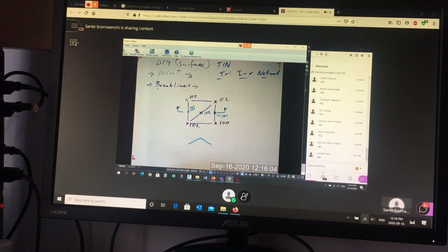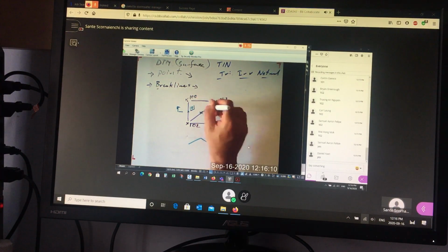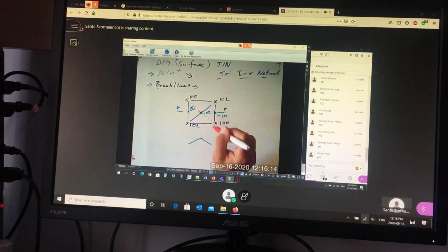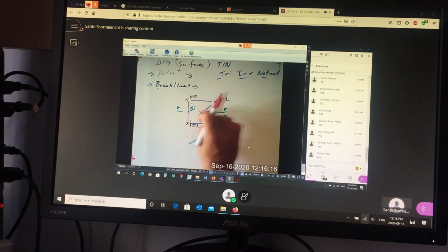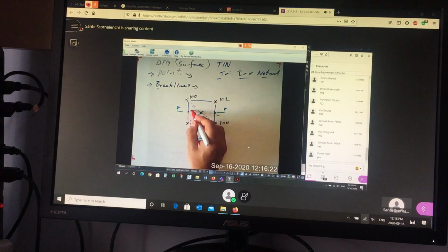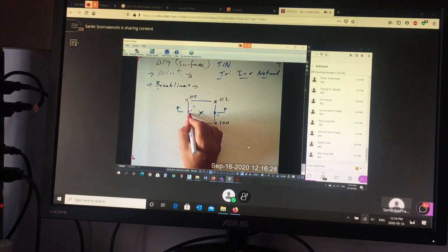Okay, so now I'm going to look at a different solution for the triangulation. Instead of this diagonal, what if the solution was this? What if we get rid of this? What would the elevation of those 3 points be now? What's the elevation here? 101, correct.